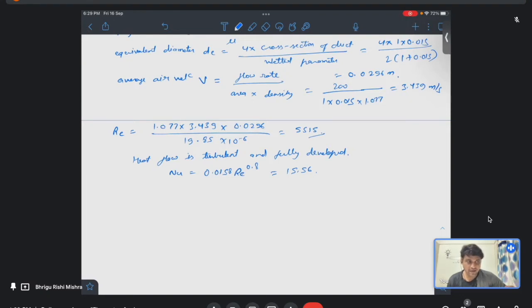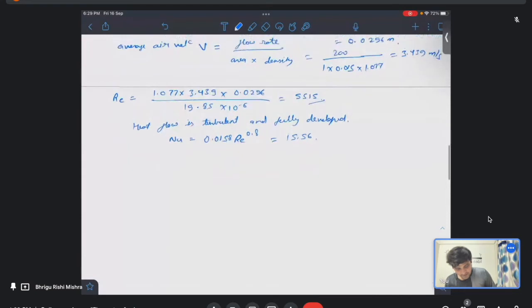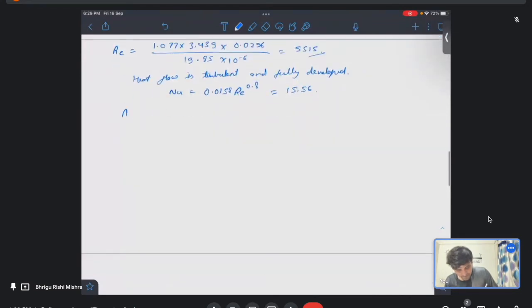Okay, so now here one assumption we need to consider: that HFP and HFB, that means the coefficient between the top plate and air and between the bottom plate and air, are equal. This is a fair assumption because both have similar material, and since air is also flowing and the gap is not very high, we can consider this assumption.